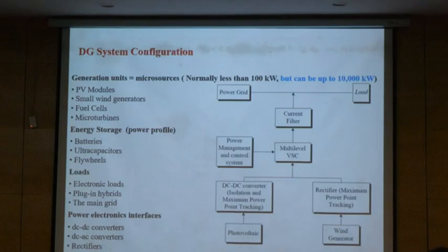So when we are talking about power quality, we need high power quality. In fact, we need high voltage quality. Why? Because P or S is equal to V times I, voltage times current. Voltage is with the provider, but current is the load side. So now this light is on, and in 10 seconds you can turn it off and turn on something else, so the current is always changing.